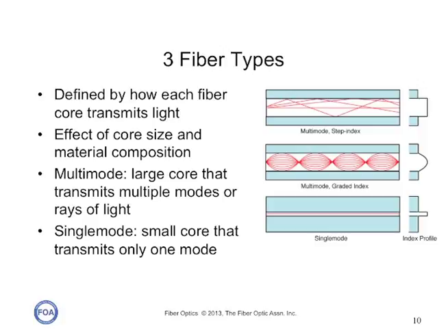There are three basic types of optical fiber that you will hear us talk about. Multi-mode step index fiber, shown at the top, just has light bouncing around inside it to carry it through the core of the fiber. Graded index multi-mode fiber, however, guides the light with a special core design that ups the bandwidth 100 times faster than multi-mode step index fiber. But single-mode fiber restricts the light to one ray of light going straight down through the center, and that's how it gets much, much higher bandwidth than the other multi-mode fibers.